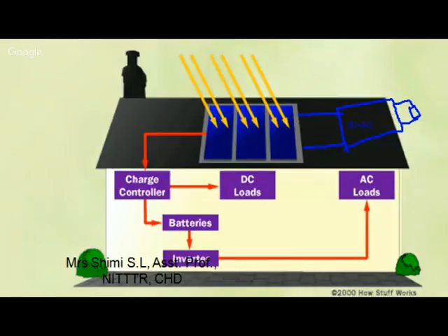Okay, is it clear? So now, when will maximum power transfer from this source to load? कब transfer होगा? Electrically think करके बताओ कि कब maximum power एक source से load में transfer होगा? मैम इंटरनल रेजिस्टेंस impedance match होना चाहिए according to maximum power transfer theorem. Whenever the source impedance is equal to load impedance, maximum power will transfer.